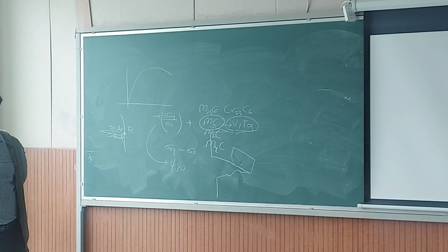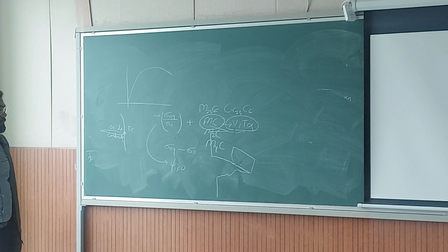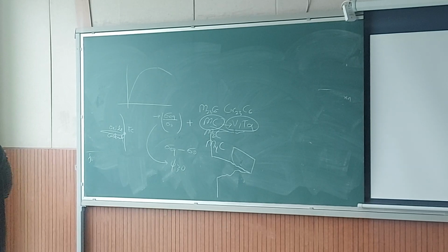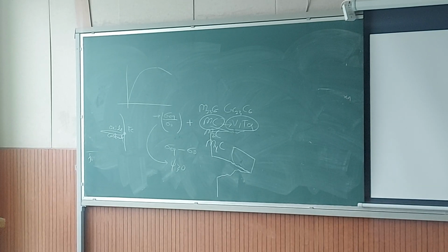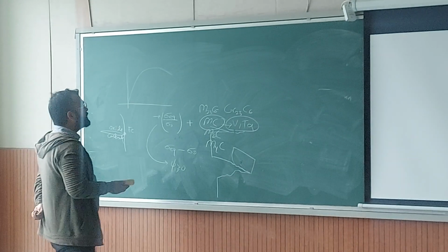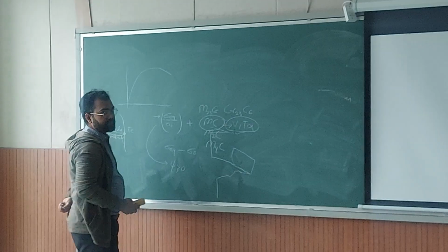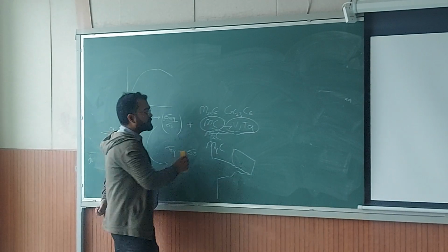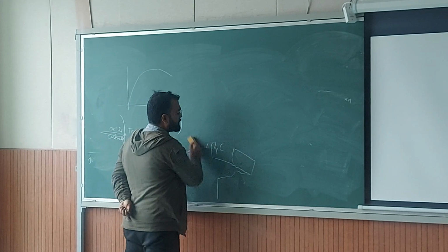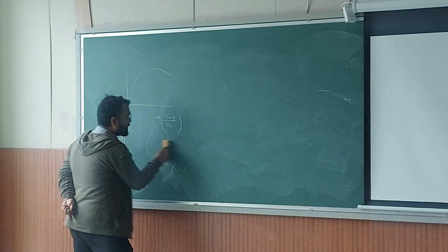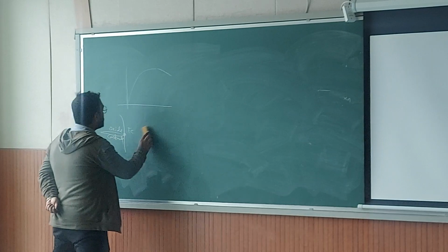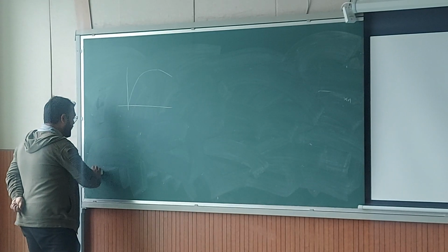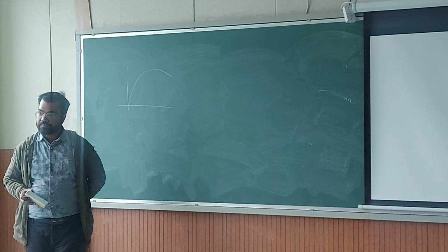to this particular steel. Okay, so you have a lot of distribution of secondary phase. One way to look at it is that we shouldn't have secondary phases, but then you will not have strengthening. We have seen precipitation hardening. So secondary phases will give you a lot of strengthening, and these carbides, they hold the grain boundary from grain boundary movement when you have high temperature deformation.